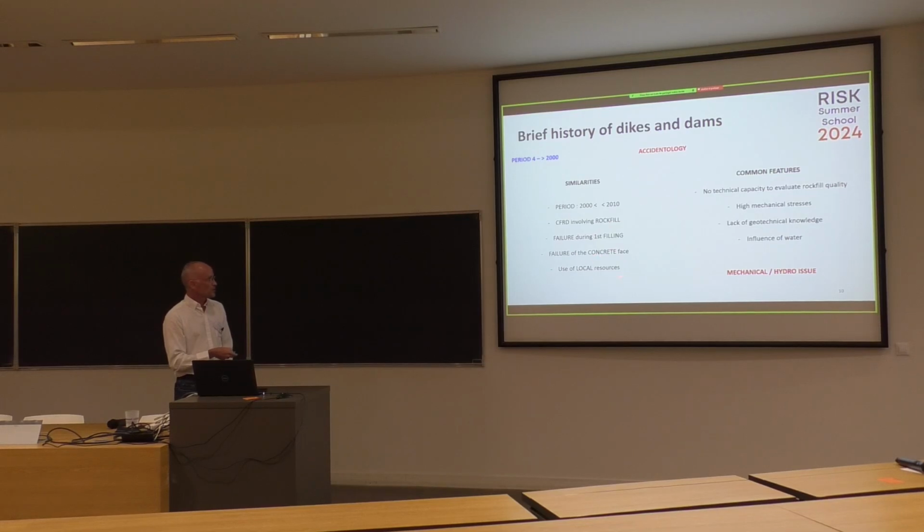And what is problematic is the use of local resources, because it's impossible to characterize the behavior of the large grains. Okay? So because there is no technical capacity to evaluate the rockfill quality, the height, so more than 200 meters, induces high mechanical stresses at the base of the rockfill. There is a lack of geotechnical knowledge.